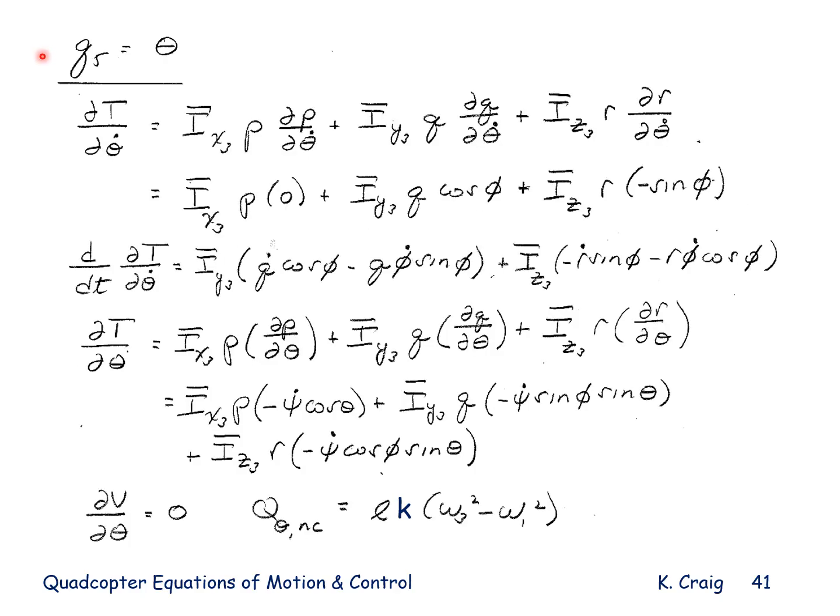I next apply the Lagrange formulation to the generalized coordinate theta, which is the pitch generalized coordinate. The terms in the Lagrange formulation are shown derived here, and the non-conservative generalized moment associated with the generalized coordinate theta is given by this expression, which is the pitch moment.